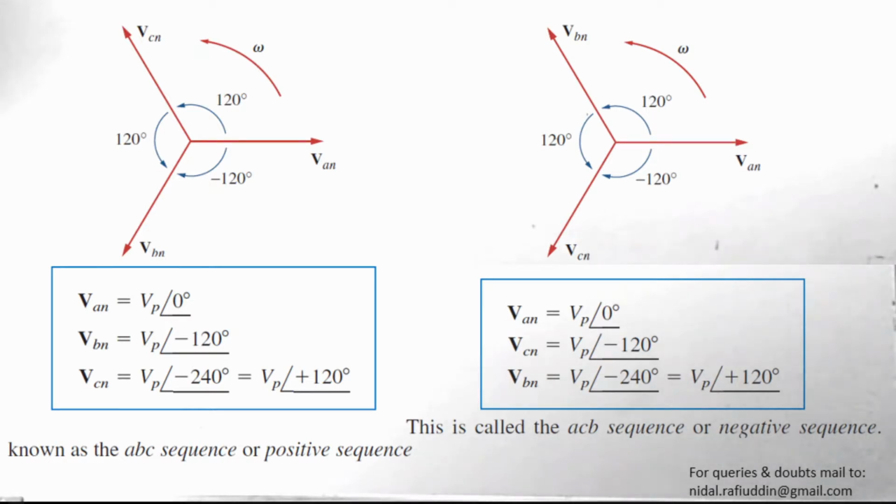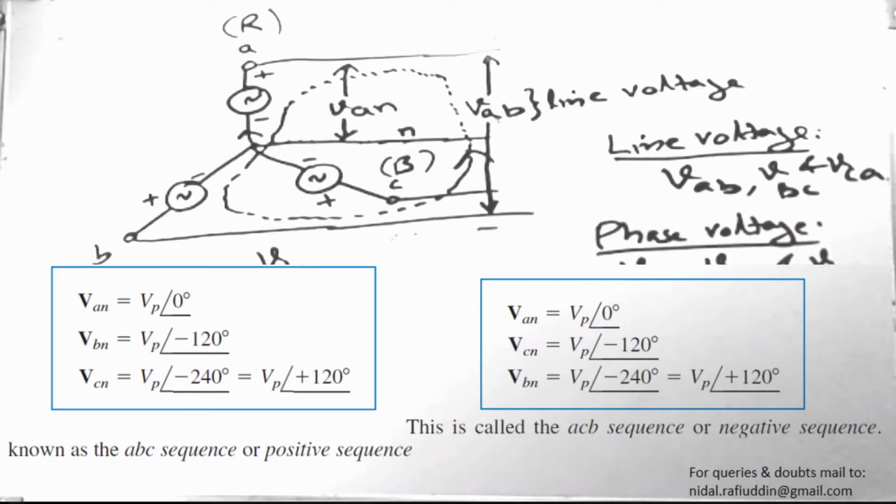Likewise, when we deal with a three-phase system, we always talk about the sequences, because in order for a three-phase system to be connected to another three-phase system having the same magnitude, this means that if we are given a sequence of ABC of a three-phase system, then that system can only be connected to another three-phase system having the same sequence ABC. If an ABC sequence is connected to an ACB sequence of another system, then that may result in a catastrophic fault.